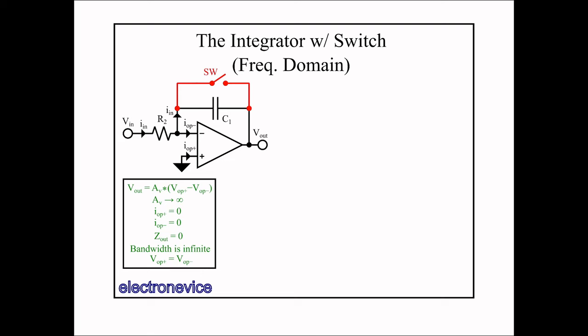An alternative to this, if a true integration is required over a specified time interval, is that the resistor can be replaced with a switch, either solid state or electromechanical, to reset the capacitor by shorting it out prior to the integration interval start. This effectively converts the integral from integrating from when the circuit was most recently powered up, with some dubious initial conditions as mentioned previously, to an integral that starts from when the switch was most recently opened. The component values can be set to ensure that the output voltage does not get close to the rails during the desired integration interval.